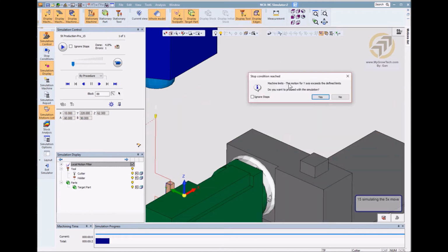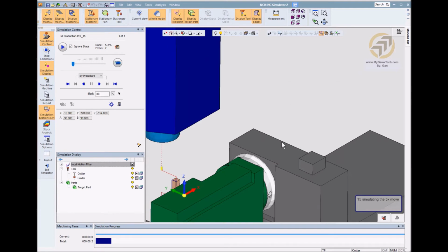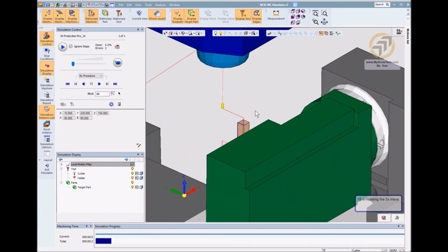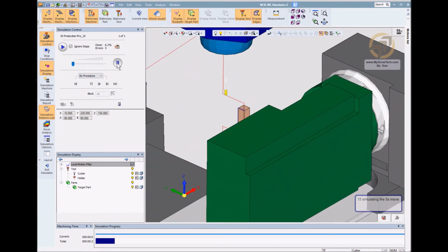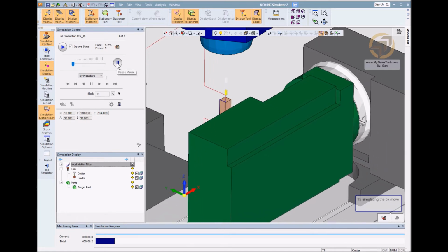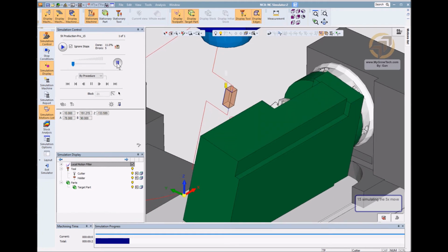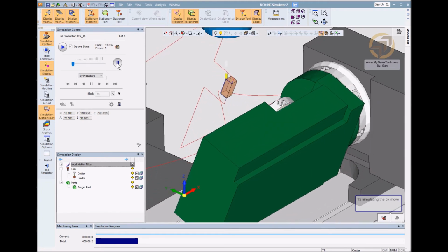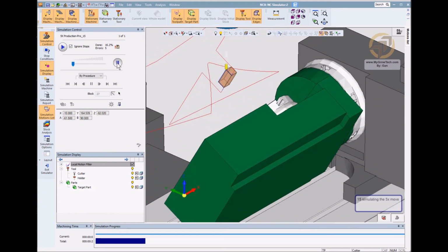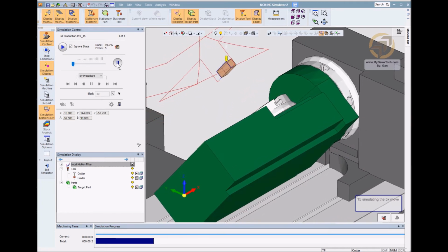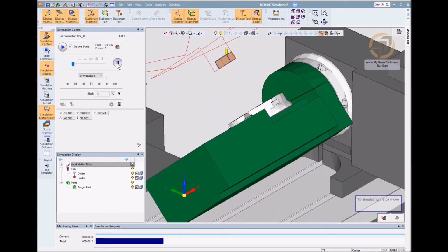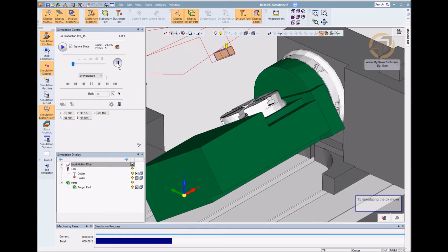There's a y-axis limit, so we need to reduce the height. Later we will edit. And let's do simulations. So we'll start from A minus 90. And the default for this limit is A0 to A minus 120. Right, so the rotary cannot go to the plus angle.